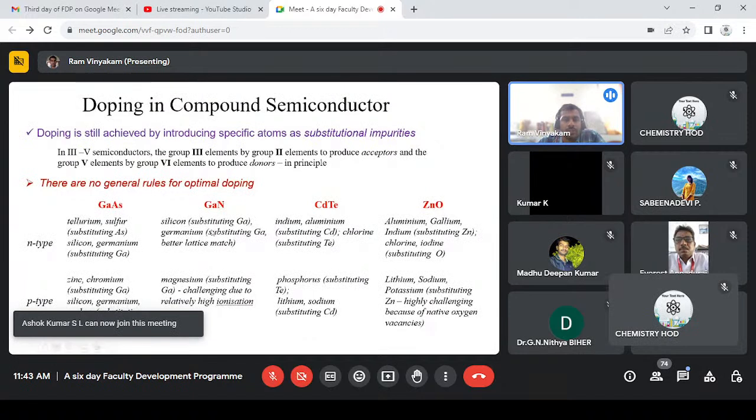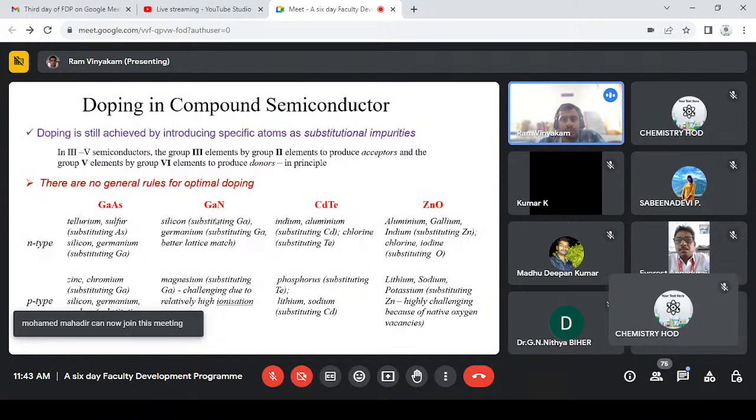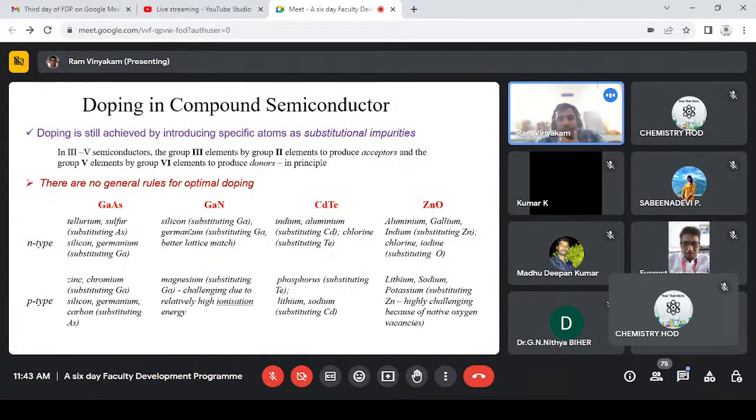And why nitrogen is not targeted: most gallium nitride is not grown as high bulk structures, it is grown in epitaxial layers. Mostly ammonia is the precursor for nitrogen, cracking ammonia to react with the gallium at a higher temperature, on the order of 900 degrees Celsius. And more, if you take aluminum, then you have to go higher. And in the case of indium, you have to come lower.